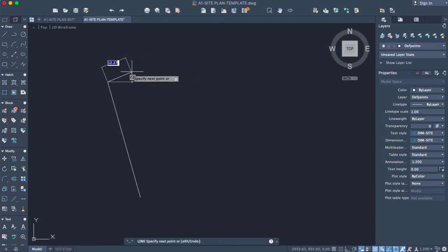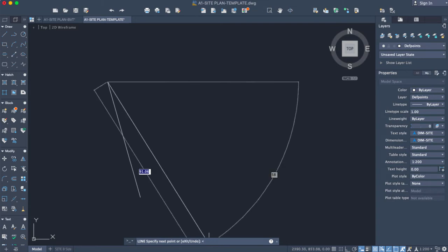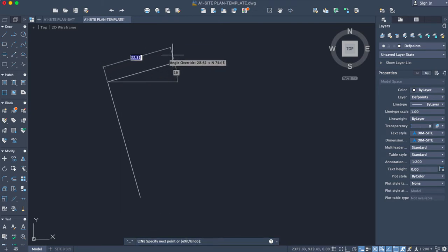Same thing when you're doing the next line, so just make sure you're putting the survey unit, which is the angle. For the next line, it is north again, 73 degrees. So just make sure you are typing D for degrees. It says 59 minutes 30 seconds east. Enter. Once you enter, your line is going in that direction.